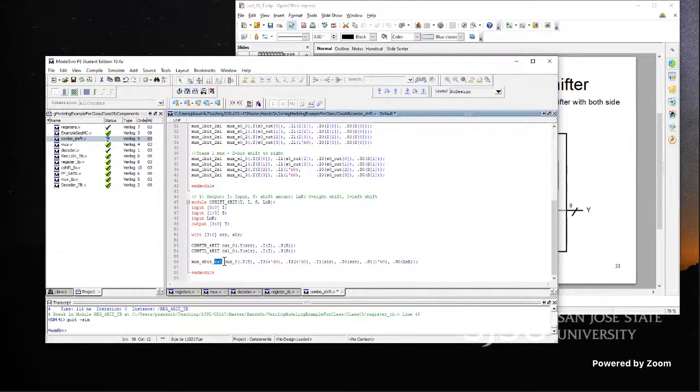I could have defined it, but I want to show you something. Even if you don't have the right component, you can still use what you have, in the real electronic world and also in the simulation environment. We still use the 4-bit multiplexer with the higher select bit S1 always connected to 0, and S0 connected to the L-and-R control.